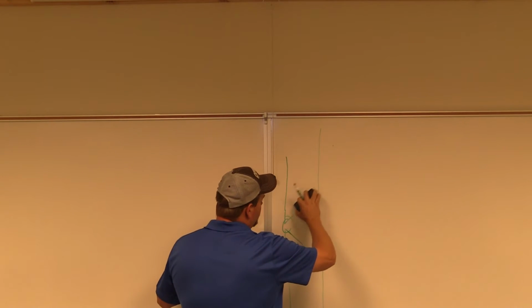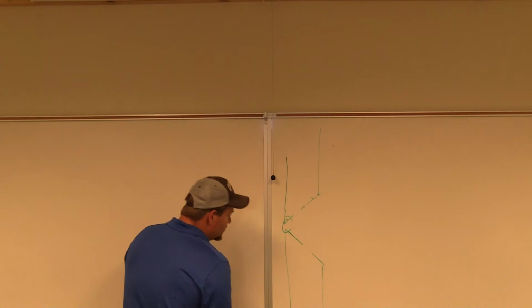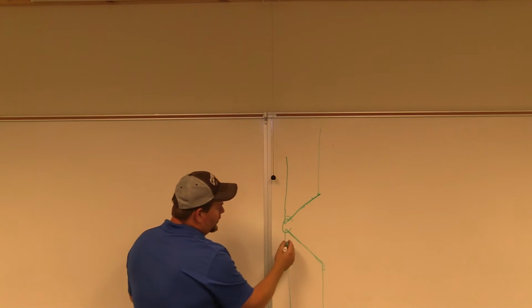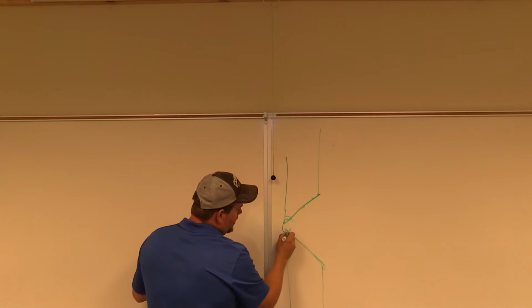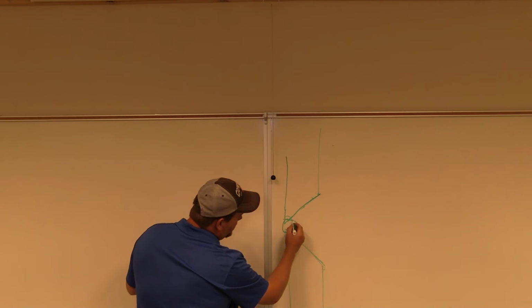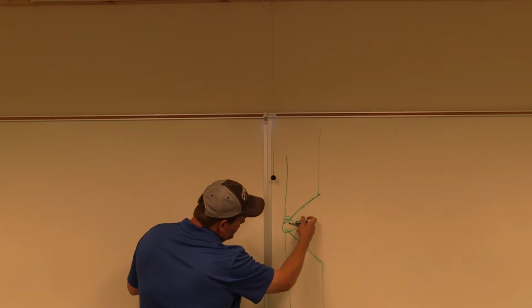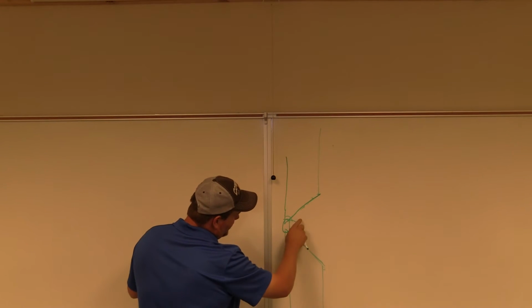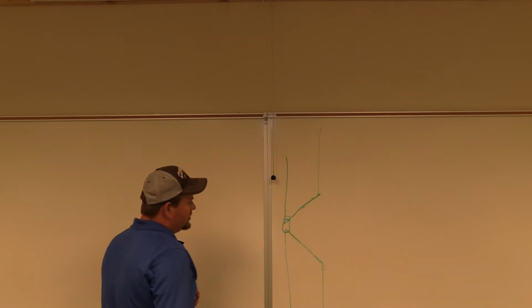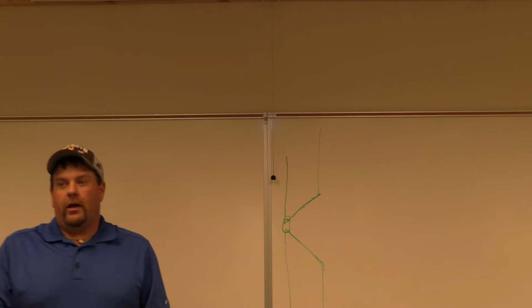and I'm using a V-groove because it's most prominent in a V-groove situation, okay? So right here on this root specifically, usually you crown up high like this. So in this case, we want to come in with our grinder and knock this down to where it's nice and flat, okay? So then we have a nice flat where we can get in here and tie into both sides. All right?